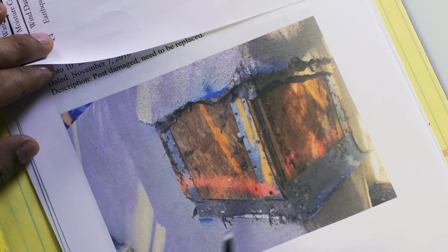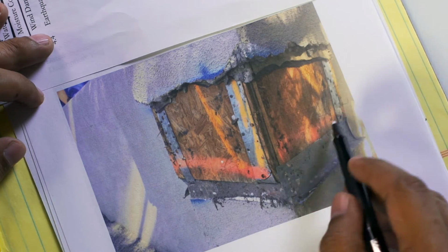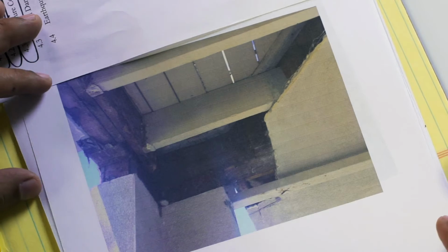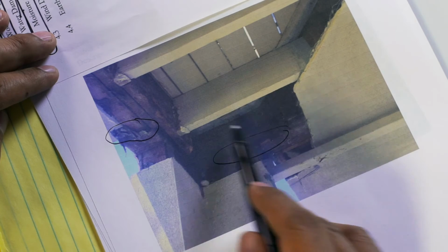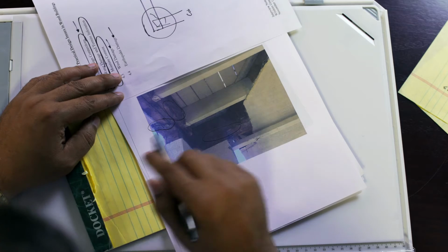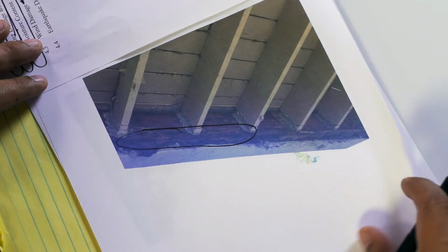You can see over here that the water damage and the termite infestation has completely warped these connections and has eaten away. You can actually see the fungus growing on the panel. This is probably the most telltale. You can see over here extensive termite infestation. This structure has to be replaced because the damage is so bad. You can see the extensive termite infestation. Here you can see extensive termite infestation, wood damage. That whole deck has to be replaced.